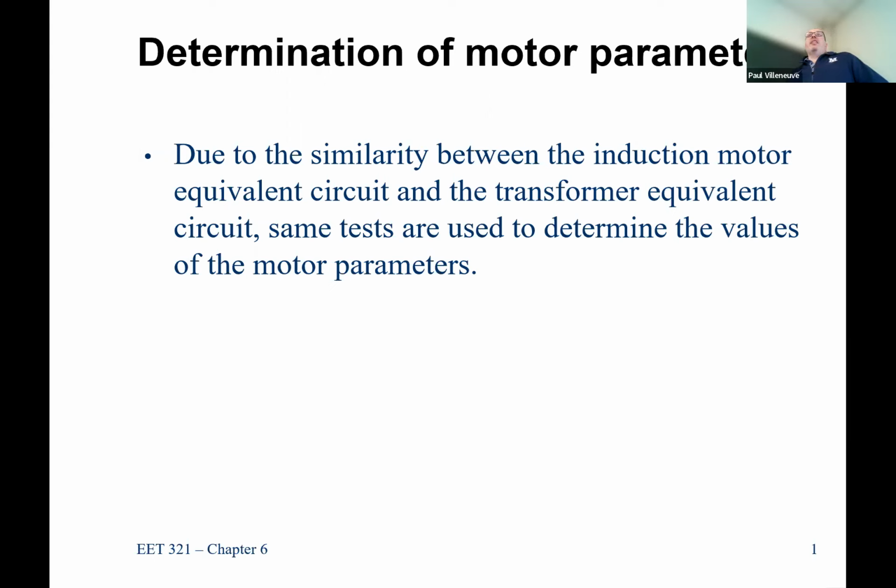You just run it without anything coupled to it. So the no load test is the test when slip is almost equal to 0. How about the short circuit or load loss test?